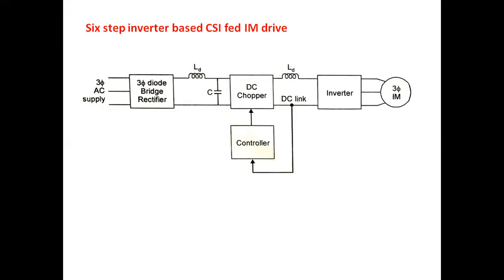Now this fixed DC input voltage to the chopper is converted into variable DC. How are we getting this? Here also one controller is kept. This controller will adjust the duty cycle of the chopper. By adjusting the duty cycle, we can have variable output voltage. It may be either step down or step up. Most probably we use a step down chopper, that is the basic series chopper.